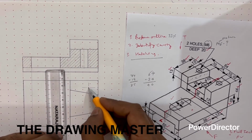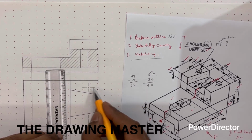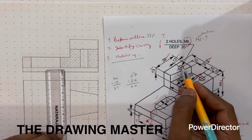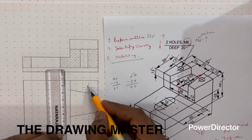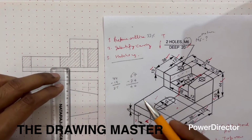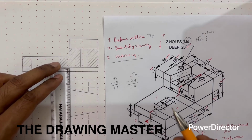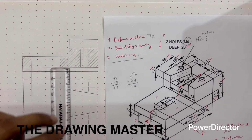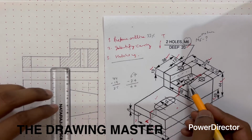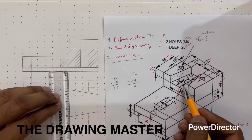So here we'll draw the holes. This is 10, 13. This is 10, 13. It's already given. 10, 13. And this is the diameter 6, as it is given M6. M6 means metric screw having nominal dia 6. So we can draw the center of this circular hole also.